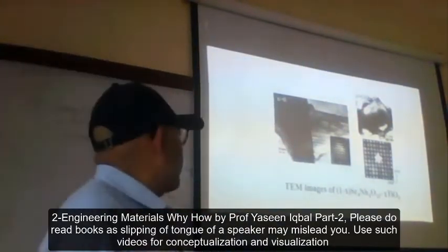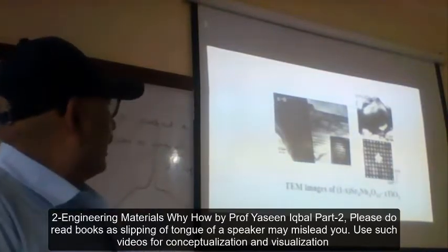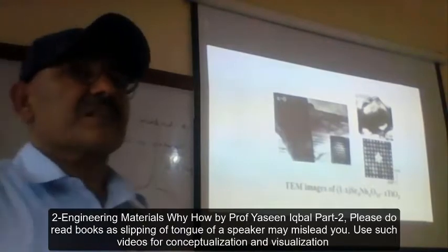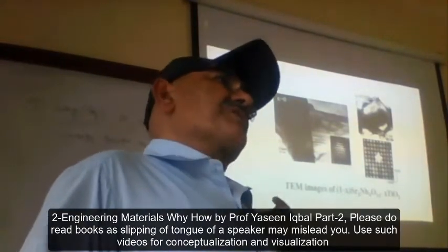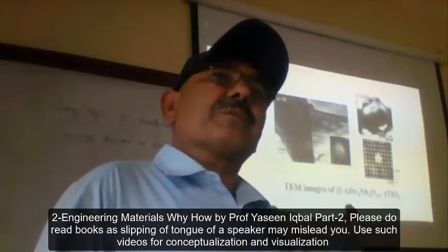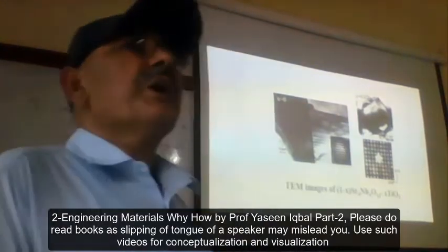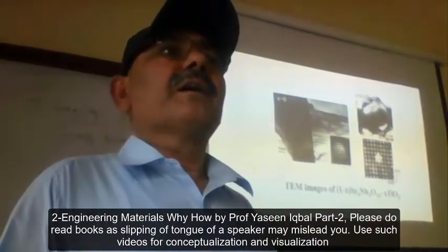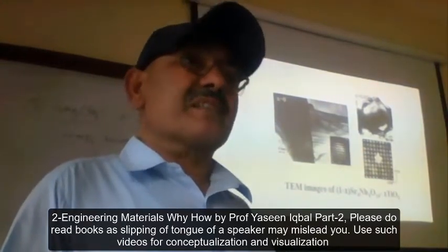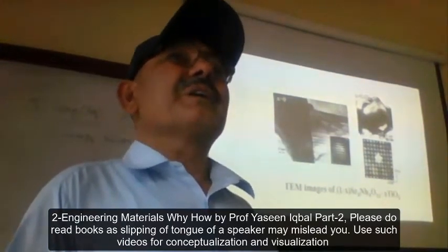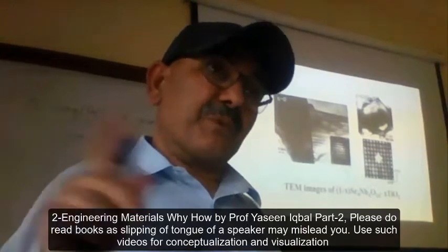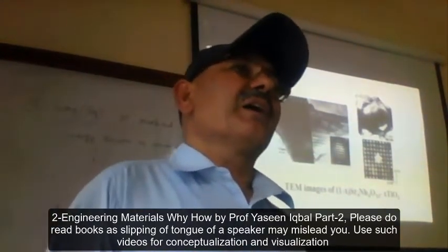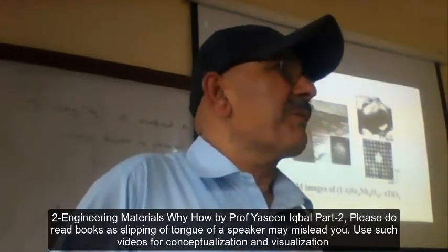Both diffraction patterns were solved, one on the tungsten bronze structure, and this one was solved on the orthorhombic strontium niobate structure. So you made the material, you processed the material, you did DTA of the material before processing, then you looked into the constitution of phases inside